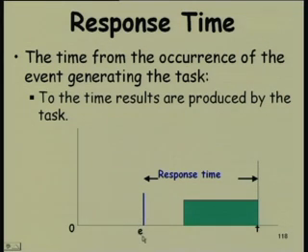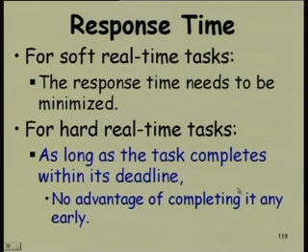The task is released at e or arrives at e and actually starts executing sometime later, because the operating system will start the task at some later time, and then it continues executing, let us say, without getting interrupted, and finally completes at t. So, the response time is the time from when it arrives to the time it completes. Looks okay? Okay.